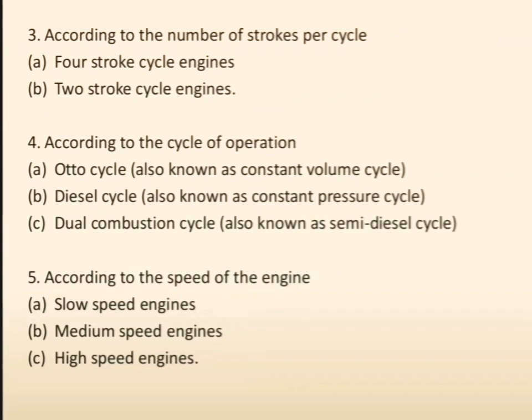In this, as the previously supplied volume is further altered by the supply of fuel into it, there is no possibility that the volume will be fixed. But for the ignition purpose, the pressure has to be maintained always to attain the self ignition pressure of the diesel. That's why they are also known as constant pressure cycle. But in case of dual combustion cycle, the cycle works partially at constant volume and partially at constant pressure.